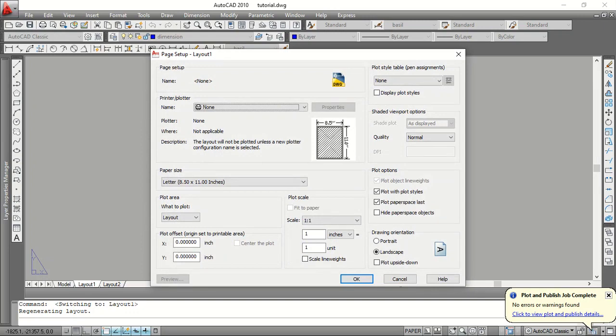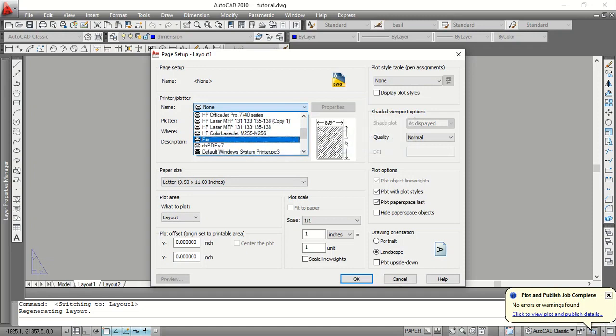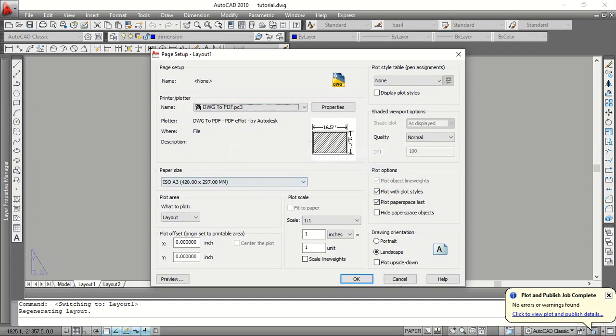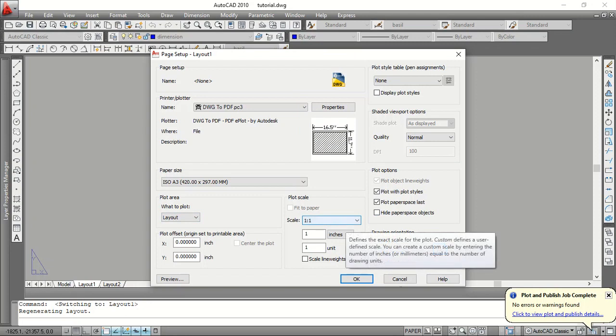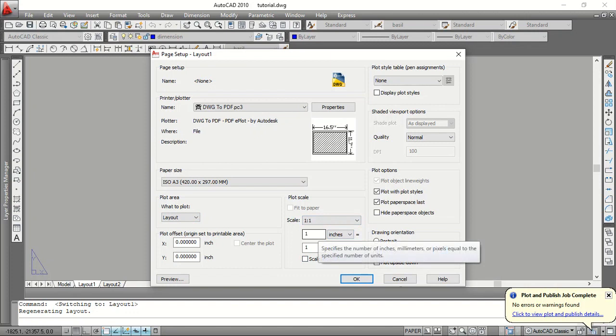When I click on modify, I'm going to do the same thing we did: PDF, drawing to PDF, okay? Click. It's going to be printing the layout because it's the layout I'm interested in. So you don't need to touch anything here. Print layout for me. Don't bother about the scale. I'll show you how to control your scale from a different page. So you don't need to select anything. You don't need to select window. Just leave it at layout.